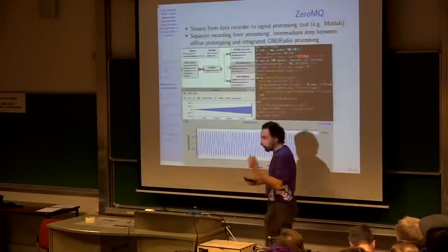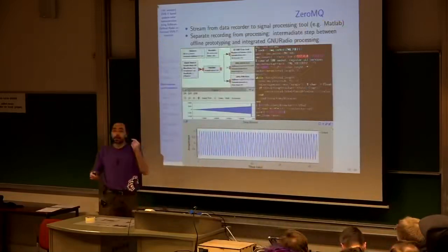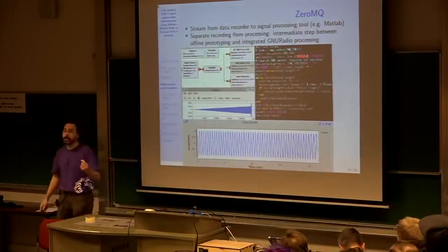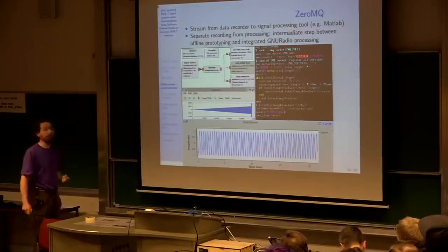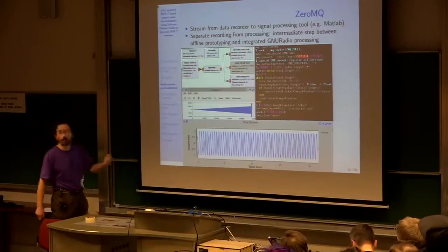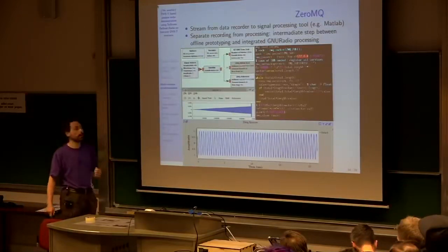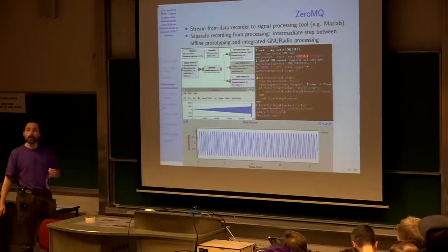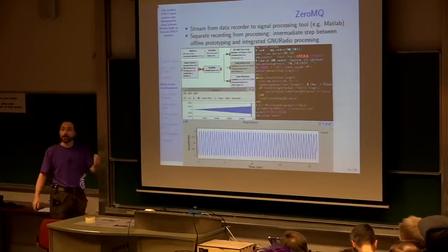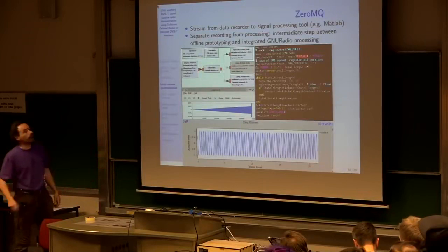Now, the problem is if we start measuring and we want to make sure that the calibration of a 0 time delay is valid for the whole measurement, we need to make sure that the data are collected and sent in a stream continuously. However, I don't want to collect data continuously because I'm generating 6 GB per minute at this rate. So how can I make sure that my stream is continuous and yet I just collect data when I need them? So here we use the 0MQ streaming.